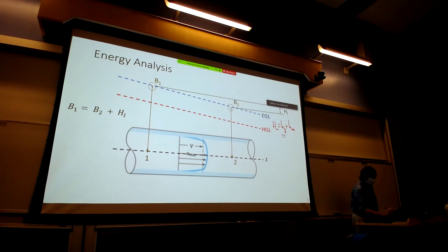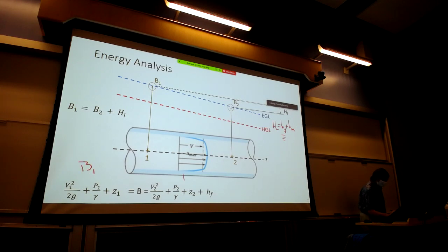So right now we're focusing just on friction loss and the Darcy-Weisbach equation describing that friction loss. And so when we set up the energy analysis or the energy balance between point 1 and point 2, the difference between those 2 again is the friction loss. And within this one equation are the 3 types of problems. Calculate h_f, calculate the discharge, which in essence is saying calculate the velocity, or calculate the pipe size, the diameter.